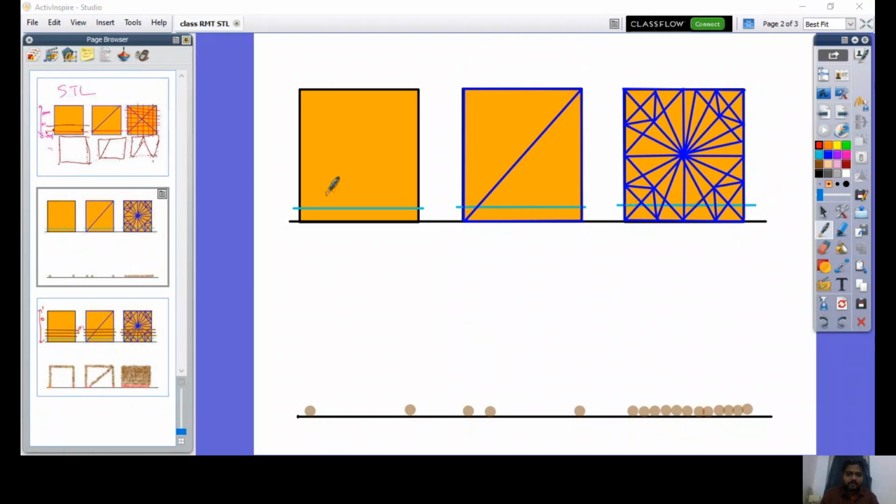The first model will have only edge information. The STL model will help you get the information between the edges, and that information will also be transferred to the machine. So the machine will go to the specific position, wherever you got an intersection. In that position, it will deposit the material. So this will be repeated layer by layer.